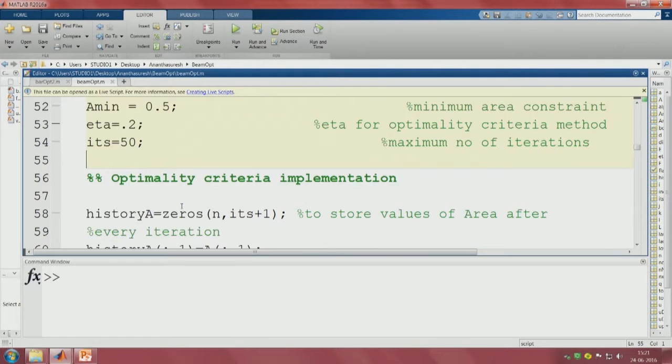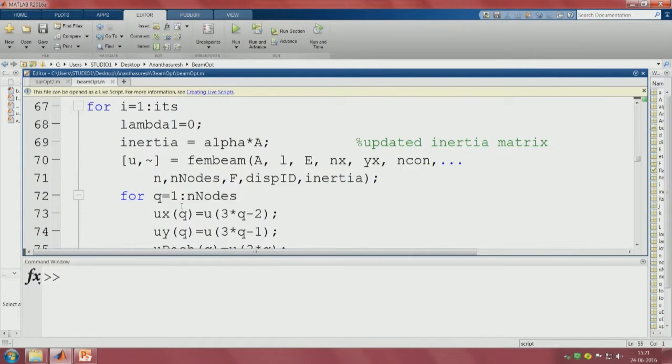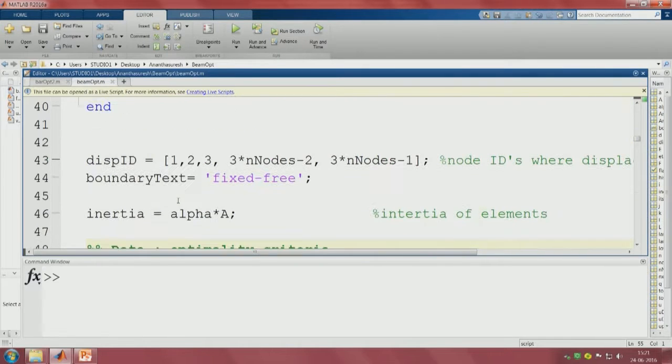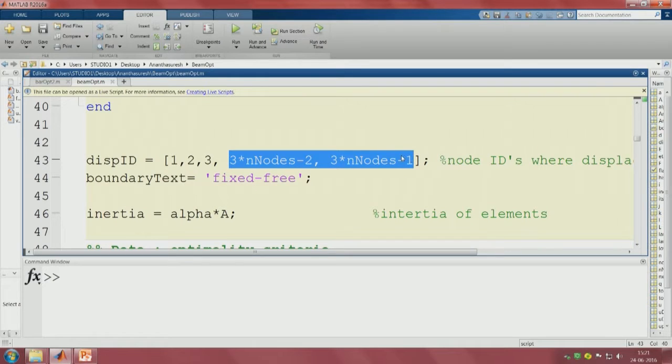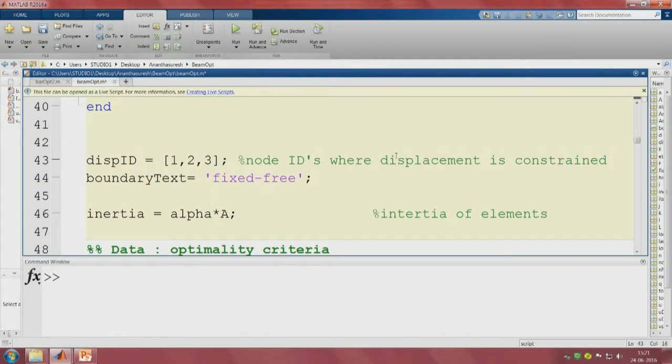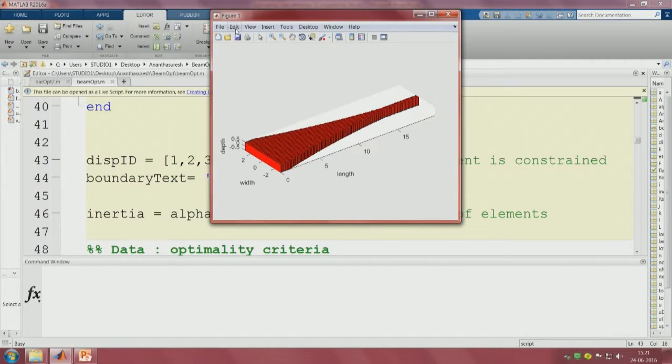So, what we will do now, going back, let us make it like a cantilever. I will remove the other degrees of freedom, completely make the other end free, only 1, 2, 3 left node fixed in x, y and the slope. So, if we do that, then we should see that part, it is coming down like a curve. In the case of a bar it was a straight line, but here it is not, and it just goes to a min at the other part.